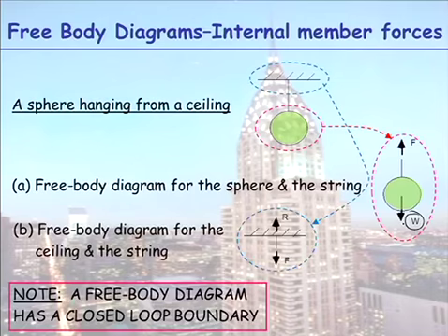We want to know what the force is in the roof. Same system. We can draw our free body diagram. We know this force down would be upwards here, to have balance, and we can work out our reaction. So again, just take note, when you draw a free body diagram, you draw a loop around everything and you include everything in the loop but nothing more. This will mean something when you come and do it.